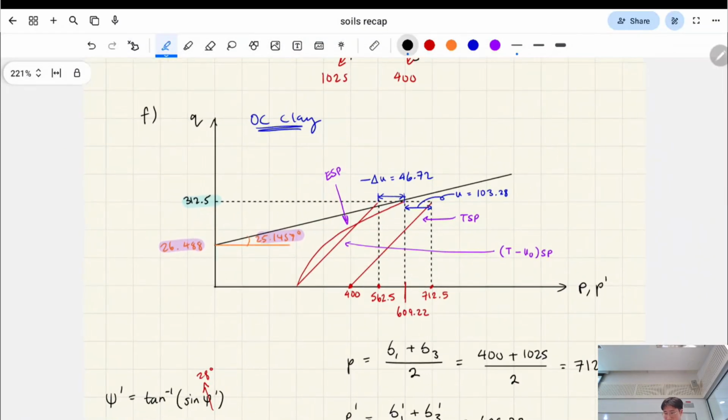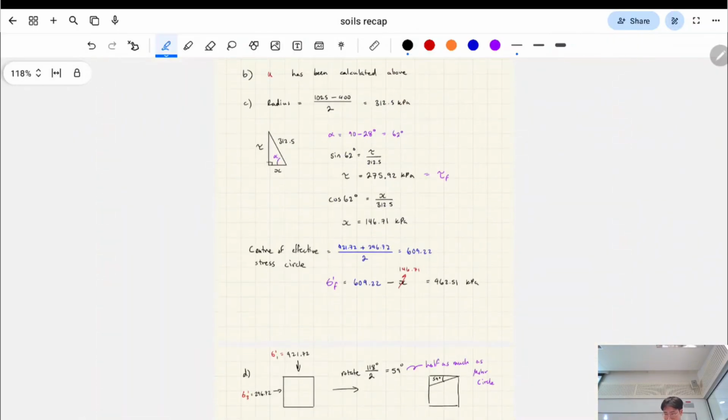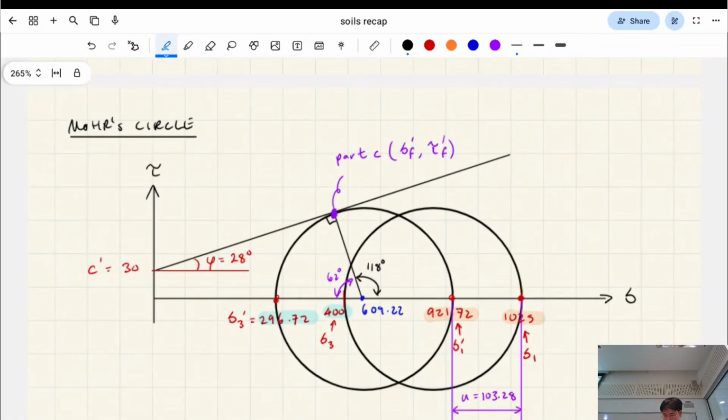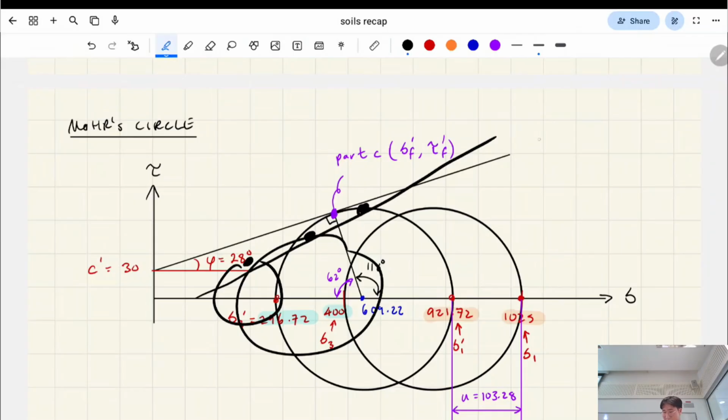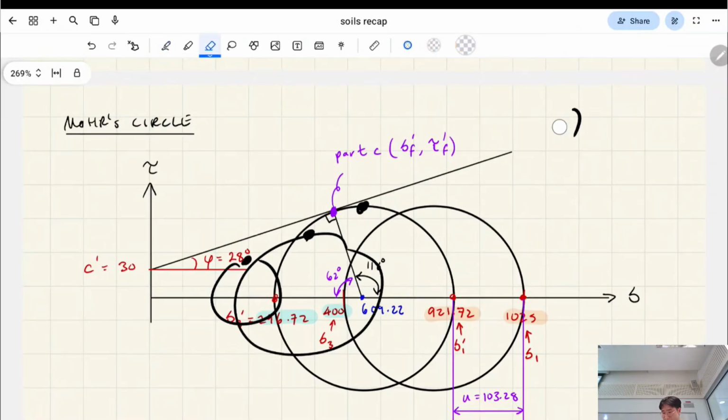Yeah, Q and P is basically, okay. So basically, as we change the pore water pressure in our triaxial test, these circles are going to shrink and grow. Stress paths is basically mapping the apex of the circle, the top of the circle, and then that line. So you'll find the coordinates of that is related to P and Q, right?